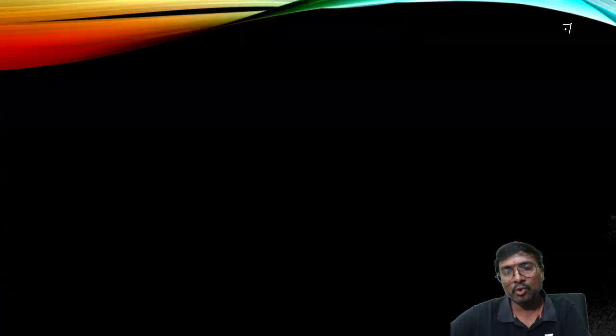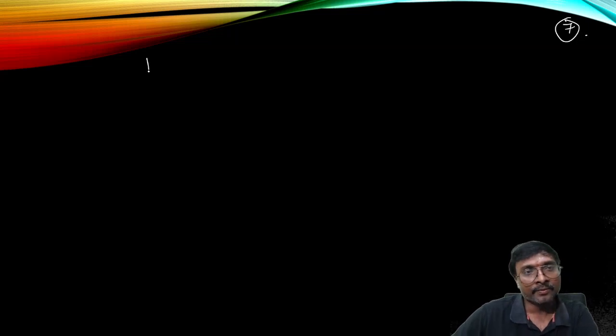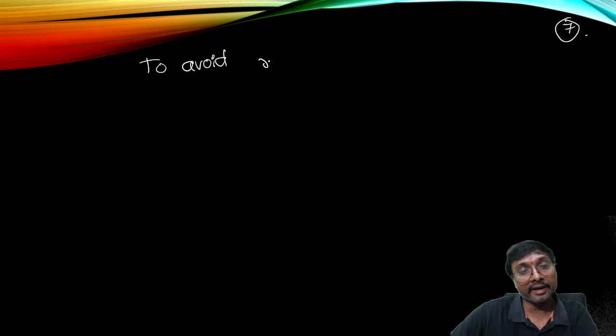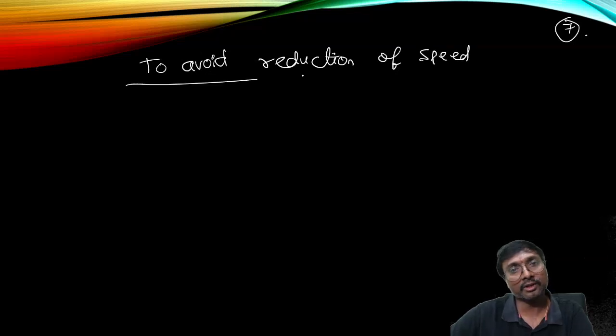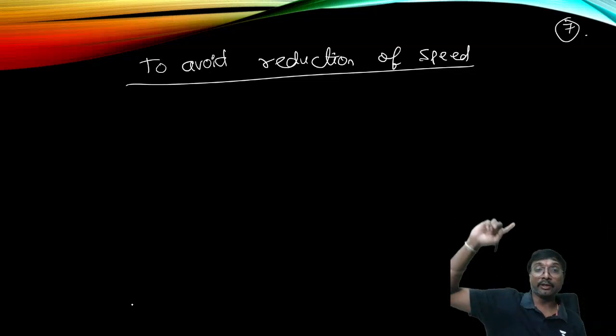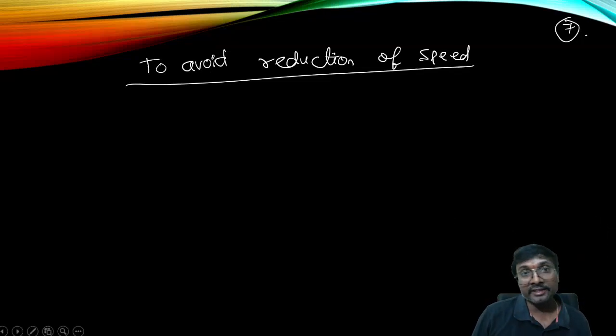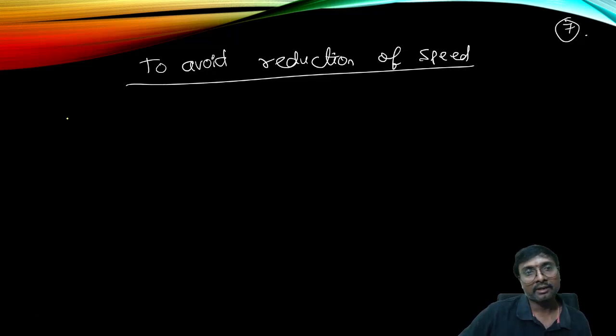Now, is it okay to allow this speed to be reduced? It is better we should not allow. So to avoid this reduction of speed, what do we need to do? We have to ensure that lesser centrifugal force comes into picture. How can you do it? Now we cannot do it, everything is over. But in the starting, when you are selecting the alignment, we can select curved alignments with a higher radius. Higher radius means even with higher speeds the centrifugal force will be lesser, right?